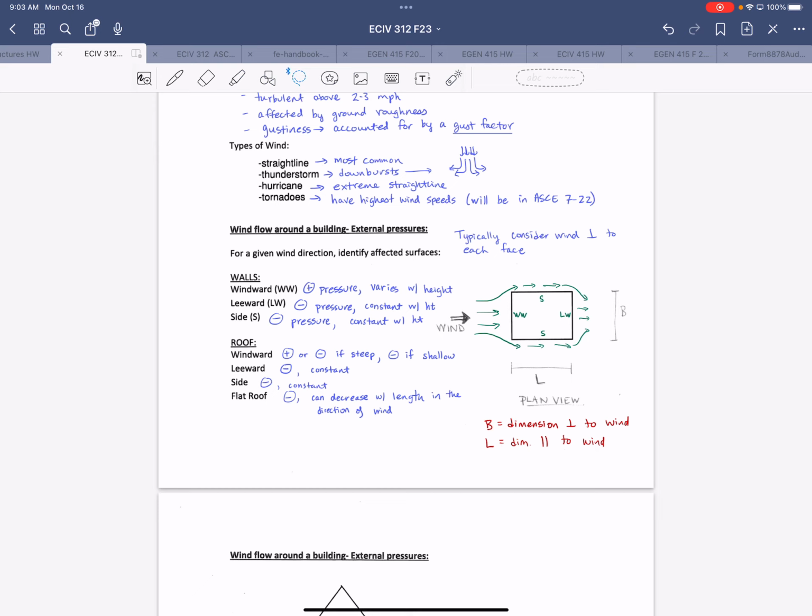And if you forget to do both of those things, then you're basically modeling that truss as a frame, which is also not correct, okay? So again, good news, beams, you don't have to change any of those default settings. You can just model the beam as a two-element system to mimic what we have in our hand calculations.